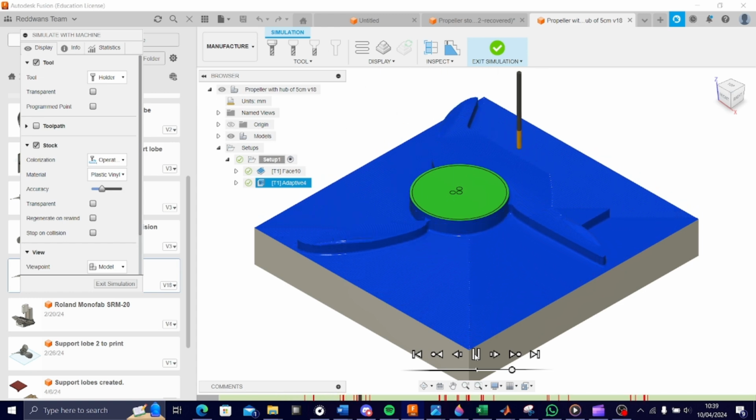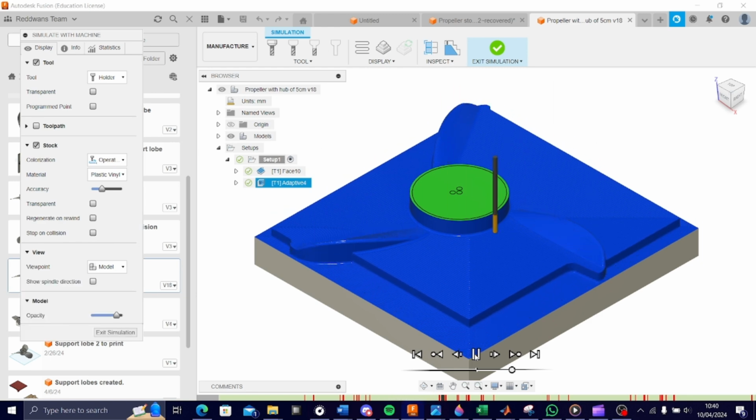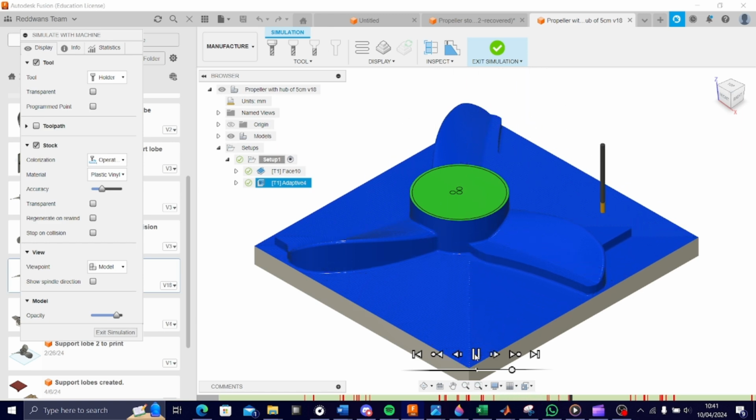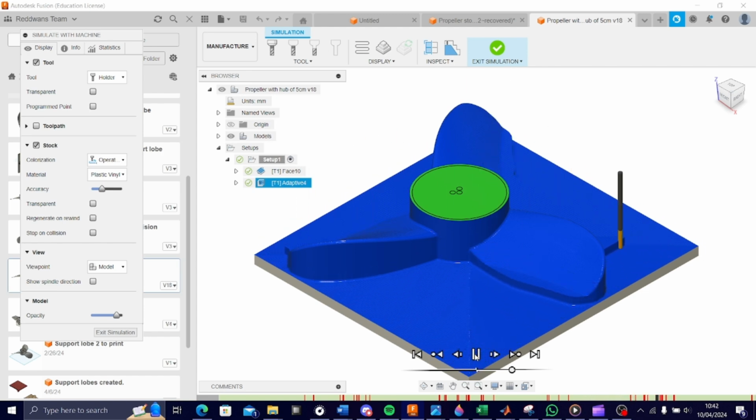From here, the ball end mill was used to do a 3D adaptive clear. The ball end mill is utilized to cut into the material to produce the object itself, and thus the 3D adaptive clear is essentially what produces the product. From here, the toolpaths generated need to be converted into a form the CNC machine would understand, and thus the files are exported and converted to G-code.